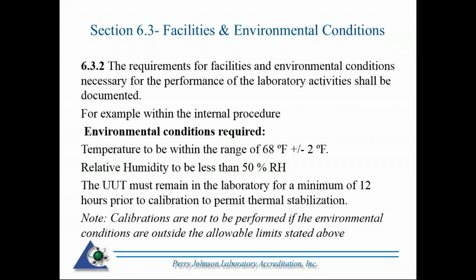If you have a test or calibration procedure specifying, for example, temperature is to be 68 degrees Fahrenheit, plus or minus 2 degrees Fahrenheit; relative humidity less than 50%; and the UUT, or unit under test, must remain in the laboratory for a minimum of 12 hours prior to calibration to permit thermal stabilization; and calibrations are not to be performed if the environmental conditions are outside the allowable limits stated above.